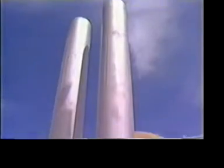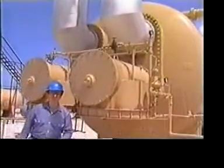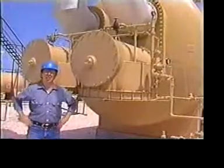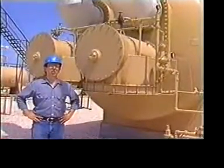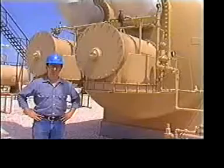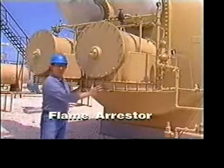Two of the most obvious components of emulsion treaters are the stacks and fireboxes. Fireboxes contain gas burners, which provide heat for the treater. Because the firebox generates a good deal of heat, a safety device called a flame arrestor is fitted to the firebox. The arrestor is a series of aluminum vanes placed close together to keep the flame from burning outside the vessel.